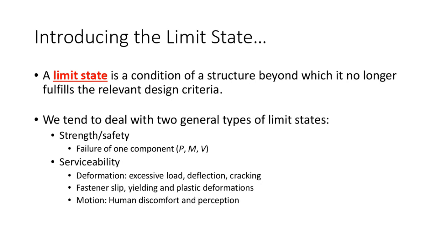So, for instance, let me ask a question. How many of you have ever been in either a house or a building that had plaster roofs, like plaster on the roof? I'm sure there's a fair amount of you that have. Okay, so the plaster on the ceiling, yeah. The beams that support those roof structures are designed to have a maximum deflection of L/360.